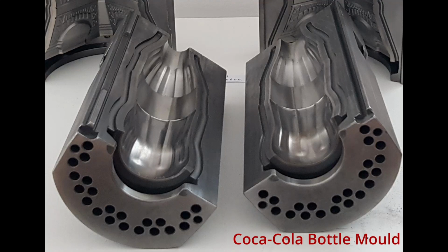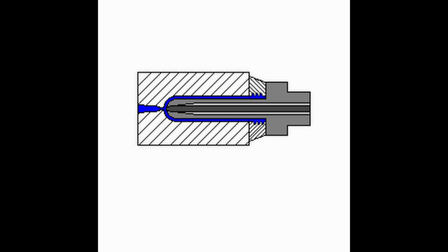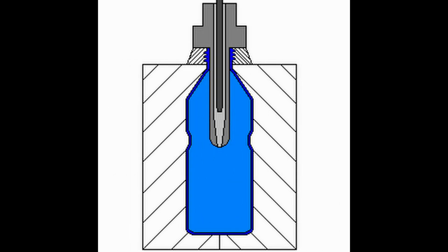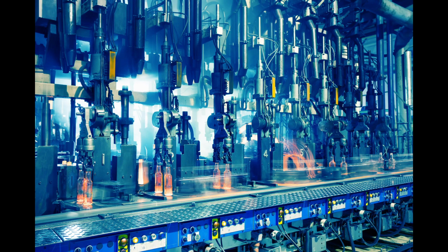The molten glass is then sheared into drops and gravity fed into a forming machine at 1200 degrees Celsius. Blank moulds shape the necks of the partially formed bottles before they're transferred to blow moulds, where reheating and blowing yield their final shape. The bottles then undergo subsequent heat treatment to prevent the formation of micro cracks and then cooled slowly to reduce tension.